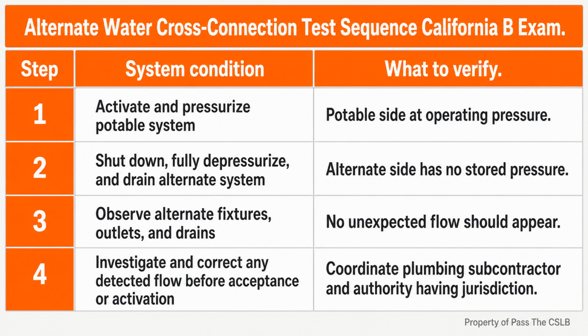Non-potable job site water systems must also be arranged to prevent backsiphonage into the potable supply. That includes temporary uses that can create a cross-connection, such as hoses serving industrial processes, mixing operations, or other non-potable work. The exact approved protective device depends on the installation and applicable requirements, but the hazard recognition is direct. Do not let a potable outlet remain connected to a contaminated source in a way that can reverse flow.